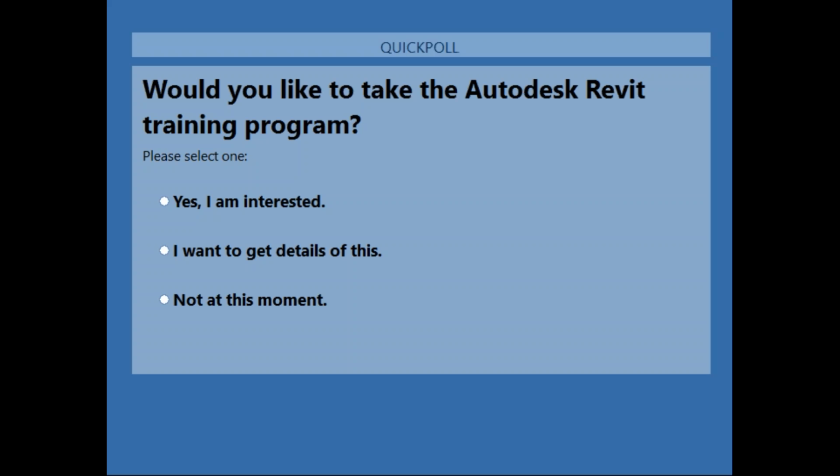I showed you that it's very easy to do it in Revit as well, but the problem it will bring is that in AutoCAD we primarily work in 2D, and when we do it in a floor plan, that's fine, but in Revit we're working in 3D modeling. So that wall actually goes all the way through the entire model of the building. So we have to go floor plan by floor plan, section by section, or every single view and create those hatches individually, the way that I showed you earlier.